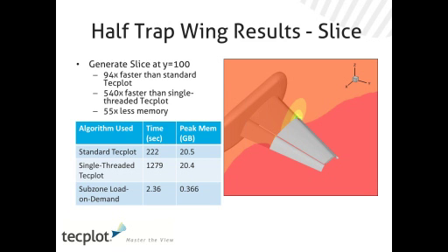Yeah, the size of the subzones is 256 cells and 256 nodes. We actually have separate subzones for the cells and nodes, except there will be one subzone left over that might be smaller, if you don't have a number of cells that's evenly divisible by 256. Yeah, that's for an unstructured subzone file. If we go to structured, we grab 6 by 6 by 6 cells or nodes, and then whatever you have left over at the extrema of I, J, and K are smaller subzones.